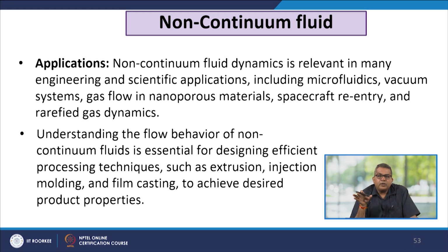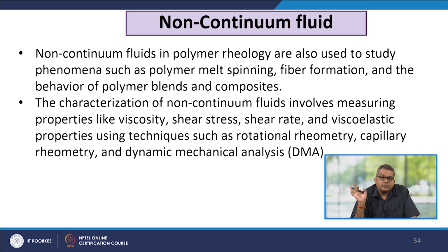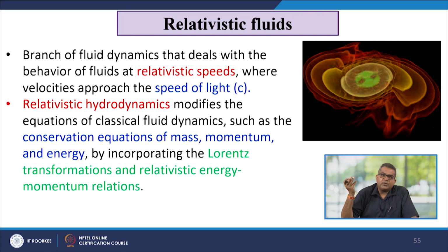Understanding the flow behavior of non-continuum fluids is essential for designing efficient processing techniques such as extrusion, injection molding and film casting to achieve the desired polymeric product properties. Non-continuum fluids in polymer rheology are also used to study phenomena such as polymer melt spinning, fiber formation and the behavior of polymer blends and composites. The characterization of these fluids involves measuring properties like viscosity, shear stress, shear rate and viscoelastic properties using techniques such as rotational rheometry, capillary rheometry and dynamic mechanical analysis, sometimes referred to as DMA.